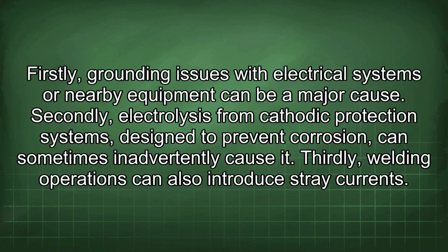Firstly, grounding issues with electrical systems or nearby equipment can be a major cause. Secondly, electrolysis from cathodic protection systems, designed to prevent corrosion, can sometimes inadvertently cause it. Thirdly, welding operations can also introduce stray currents.